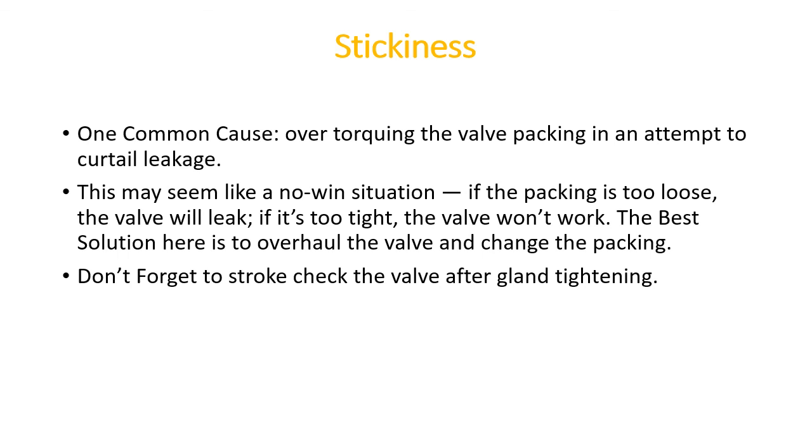So the best maintenance practice is, if you are tightening the gland, always do the stroke checking after tightening the gland. There may be a situation where you just tighten the gland and take the valve online, and the valve does not move at all, leading to a very uneasy situation, production loss, or even bigger than that. So if you are tightening the gland, always make sure you do the stroke checking after that.